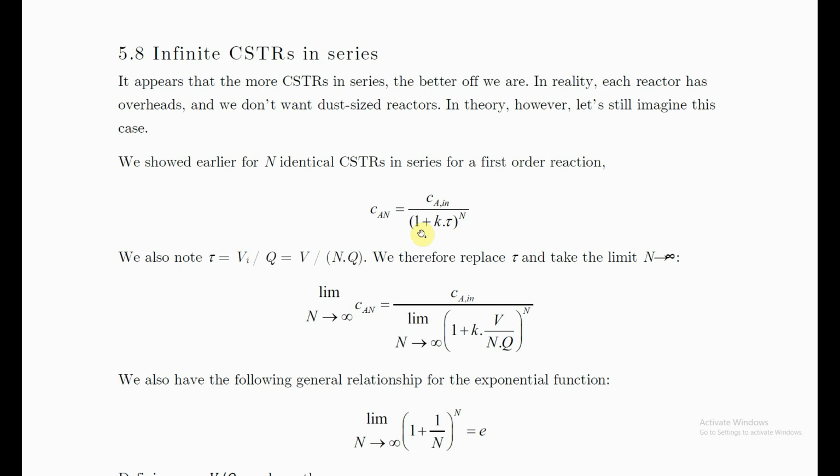so now we are not talking about minimizing total volume or anything like that. We are just going back to case 2 and saying, let's just take equal volume reactors and let's do our material balance. And we had said for n tanks in series, we get Ca in over (1 plus k tau) to the power n. Right, so go back and look at that material balance. That's what we had for n identical CSTRs in series.